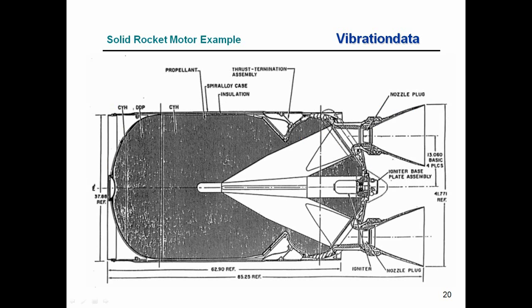So here we have a cross-section of a motor, and the dark gray is the propellant, and it's solid propellant. From what I've read, solid propellant is kind of like the consistency of rubber, like the eraser tip on a wooden pencil. And the combustion cavities are these. In this case, there are 4 exhaust nozzles, so there are 4 cavities that converge together at an apex. But these are acting like organ pipes, and again, the standing pressure waves can get set up.